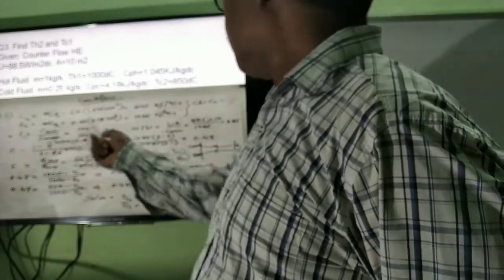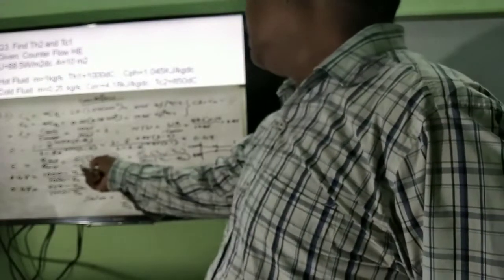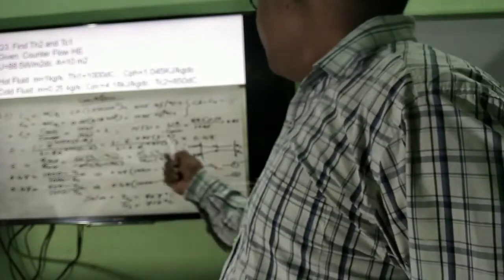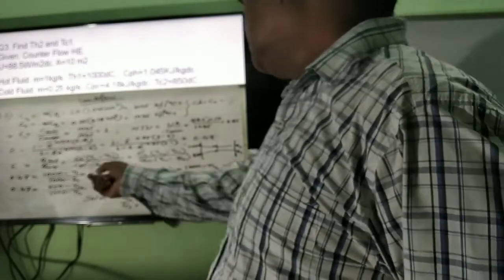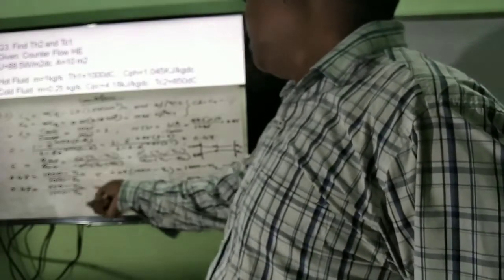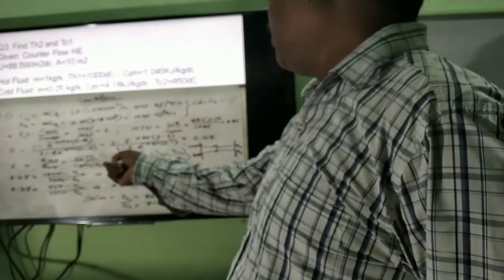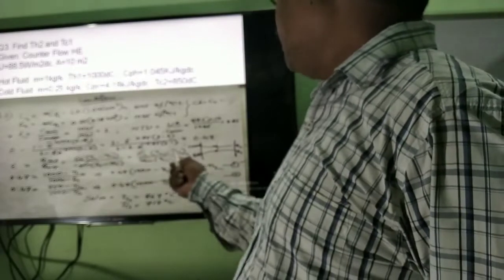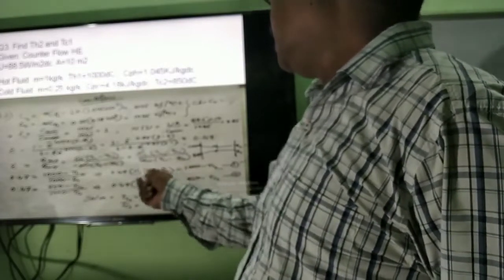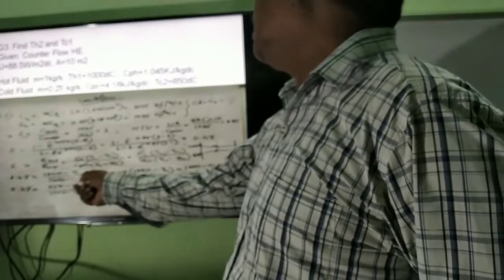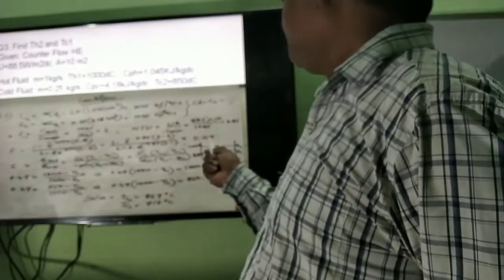The temperature difference into heat capacity, and the maximum is heat capacity into the hot inlet minus cold inlet temperature. So make the ratio, one for hot fluid, one for cold fluid. So you will get two independent equations. Put both independently equal to the effectiveness, that is 0.47.